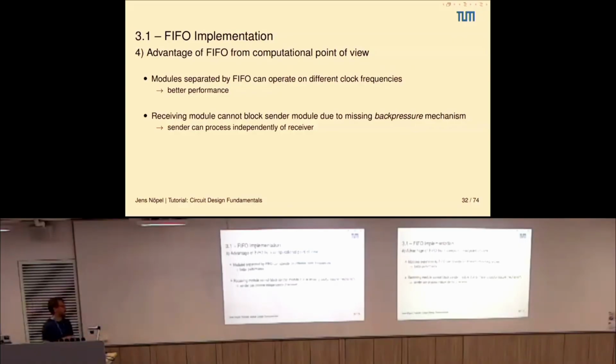The other thing is that the receiving module cannot block the sending module due to missing back pressure mechanisms. Let's formulate it differently. If module B is busy doing stuff and cannot receive data from module A, it would directly block module A from creating data if there isn't a buffer in between. So module A needs to wait until module B is ready to receive data and then can continue processing as well.